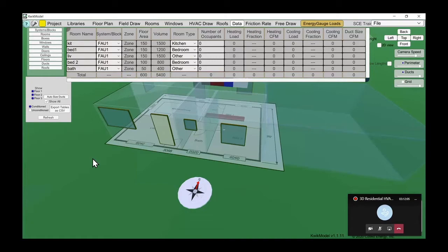If you know otherwise and can defend your assumption, you can put in a different number. But unless you know, do not let a homeowner tell you, "I have parties with 50 people and I want you to size my air conditioning system for 50 people." Don't do that. That's not a good design practice. If you want to know how much impact it has, you can plug those numbers in, do the load calc and look at it, but I highly recommend that you don't design your system that way. I'm not here to tell you how to design. I'm just telling you what Manual J says, okay?